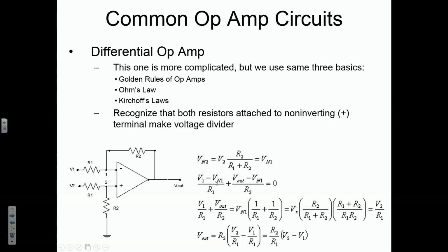So plus V out minus the voltage at node 1 divided by R2, and we set that all up equal to 0. Now, we're going to do a little bit of manipulation of the position of terms here. We're taking the voltage at node 1 terms here and putting them over here. Okay, that's all we've done.